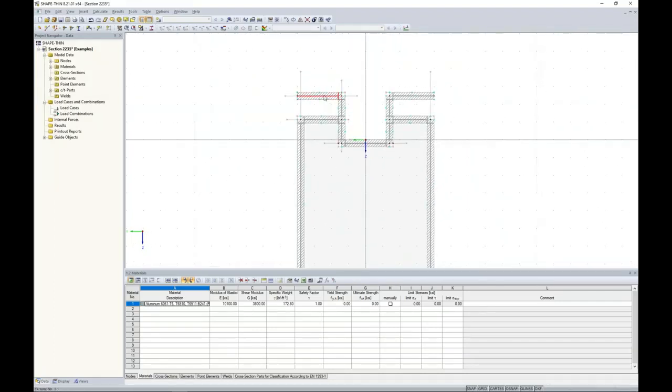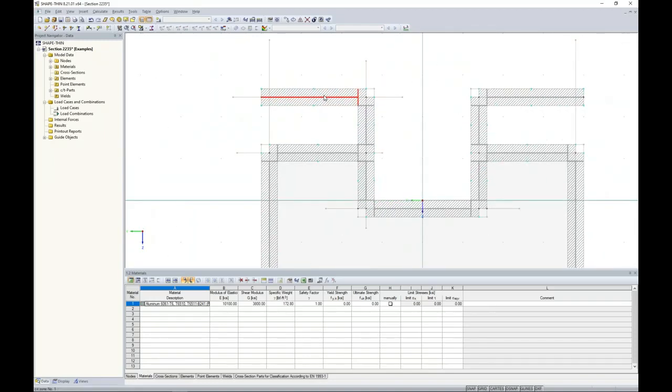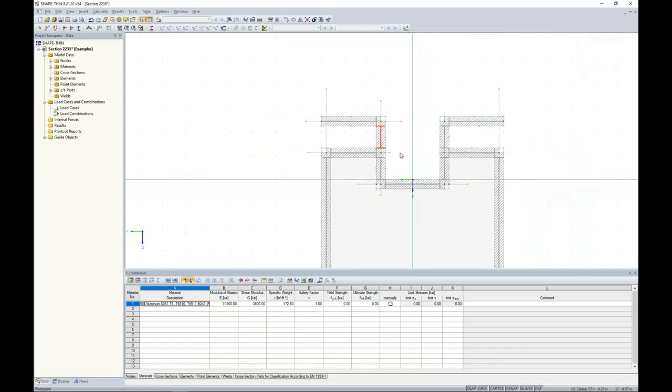It does create a couple little small segments here that I can just simply delete with my keyboard. Now, you'll see these symbols at each element, and this is the width to thickness symbols, those C over T parts. So this is what's recognizing width to thickness, but even more so, you'll notice that at these closed ends we have what looks like a T symbol, but at the open ends we don't have that same symbol. So this again is important for aluminum design to tell the program how the edges are supported. And over on the right hand side we can see that it's supported, but over on the left hand side it's not supported. Again, important for local buckling. When we look at one of these other elements that's supported on both sides, we see that T-type symbol on both sides.